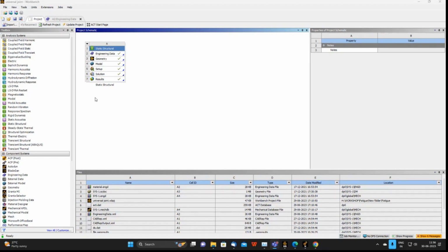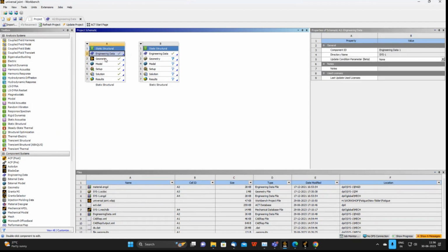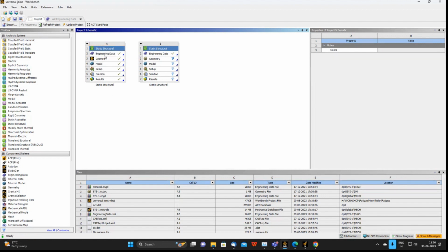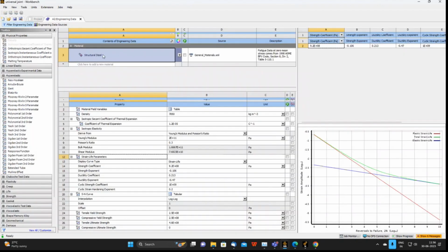The first and foremost thing, we need to have the material details to estimate the fatigue life. For the first thing, we need to drag and drop this structural part, or whatever analysis you are performing. And then the stepwise procedure: we need to include the material data, import the geometry, and then comes the boundary condition and loading, then the post processing things. Let's move into engineering data.